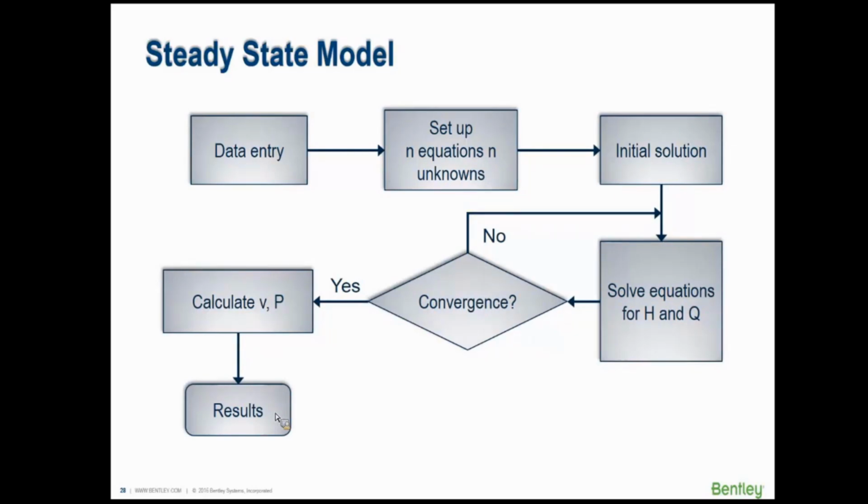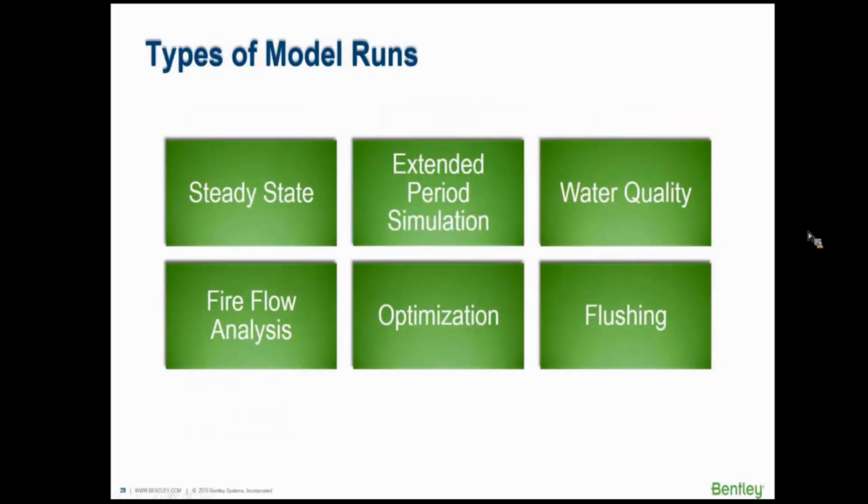But there are a whole variety of other modeling applications that we have. A steady state model is the simplest kind of model, and that's what we're going to learn in the first workshop. But then we want to see, how does the model behave over time? And that's where you get into extended period simulation, where you watch flows changing as the water use changes over the time of day, and pumps come on and off, and tank levels go up and down. But then once we have these solvers that can solve pipe network equations, we can do all sorts of things.